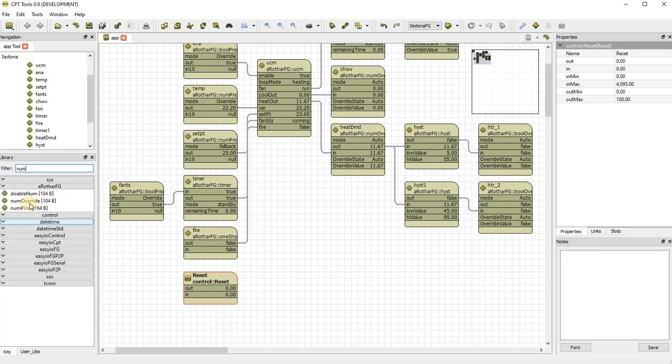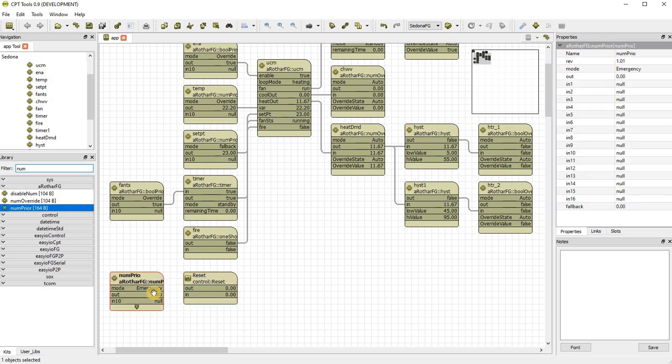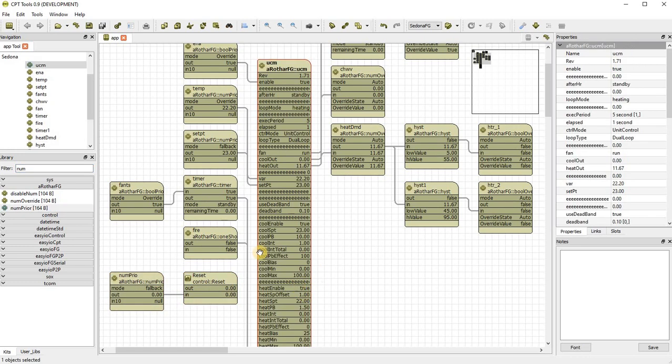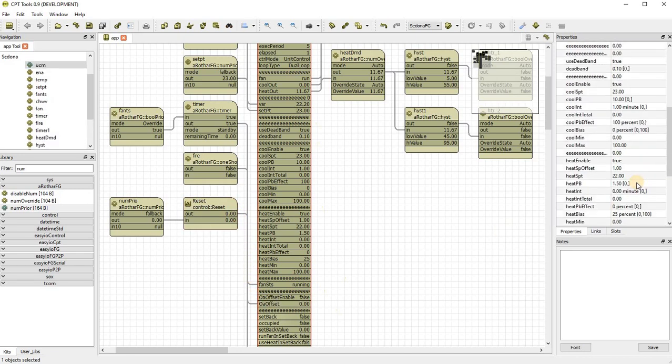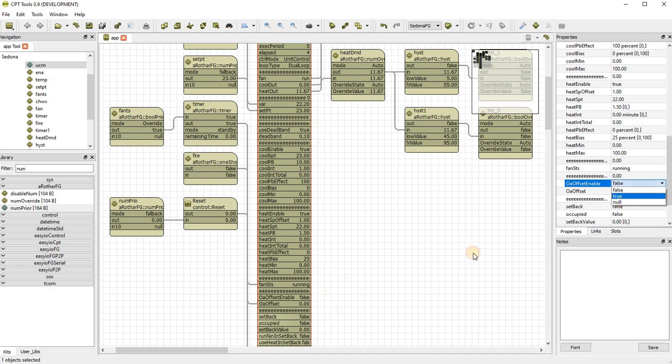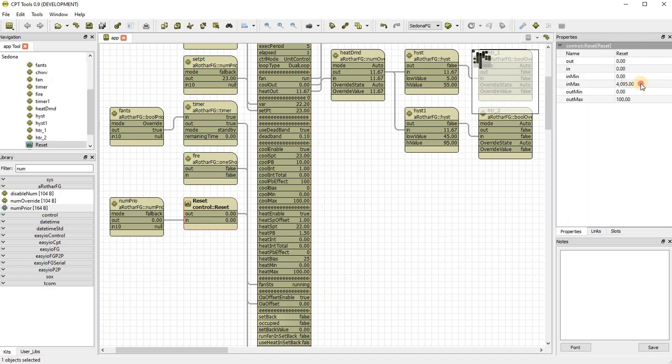It didn't work as well as I wanted. Priority. Okay. Put that into our outside air offset. Let's turn that offset on. True. Okay, so our reset will be, let's call this, I don't know, 10 degrees Celsius to 15 degrees Celsius gives us minus 1.5 to 0.